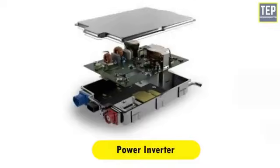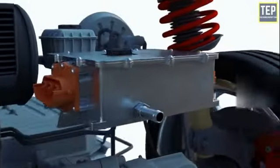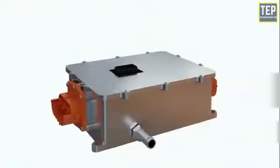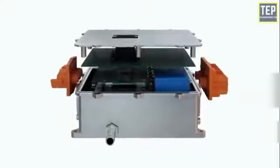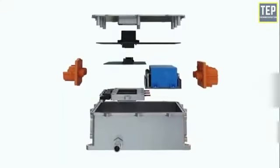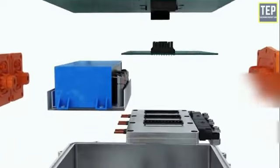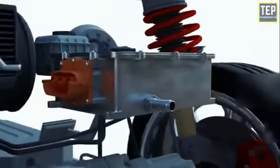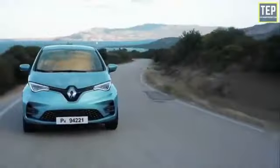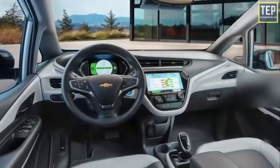Power inverter. The inverter functions to change the direct current from the battery into an alternating current, and then this alternating current is used by an electric motor. In addition, the inverter on an electric car also has a function to change the AC current during regenerative braking to DC current, and then it is used to recharge the battery. The type of inverter used in some electric car models is the bidirectional inverter category.